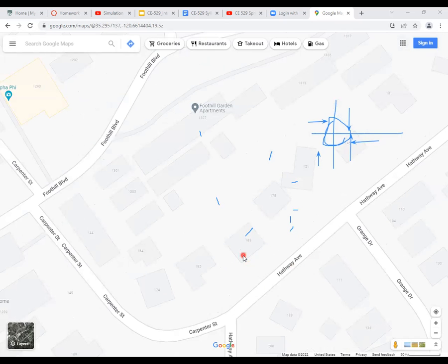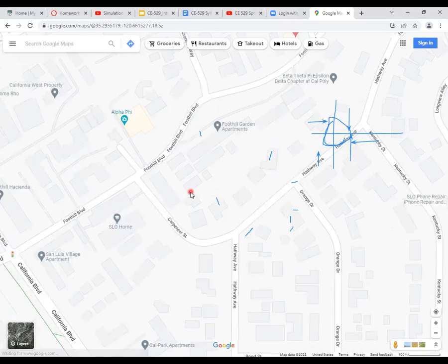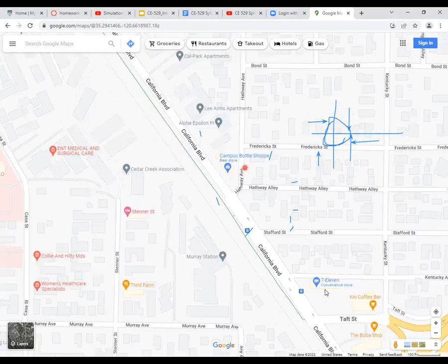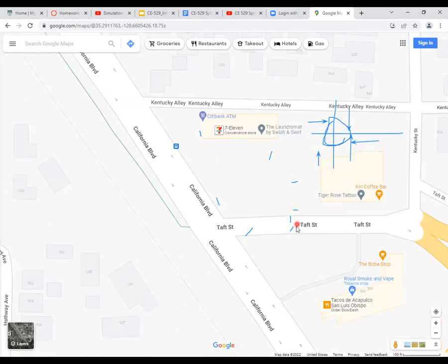So if you go back and look at this, even if you move cars to bicycles, I don't think this intersection would be impacted too much, because this is the traffic coming from North County, right? So they probably are not going to be switching. I think for them, the switching would be different. So if you say, I'm going to move 10% of the automobile traffic to bicycles, you can't just uniformly reduce your automobile flow by 10%. You have to be careful about where you make that demand adjustment.